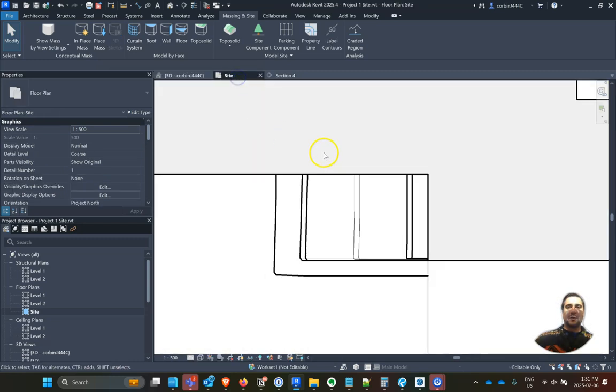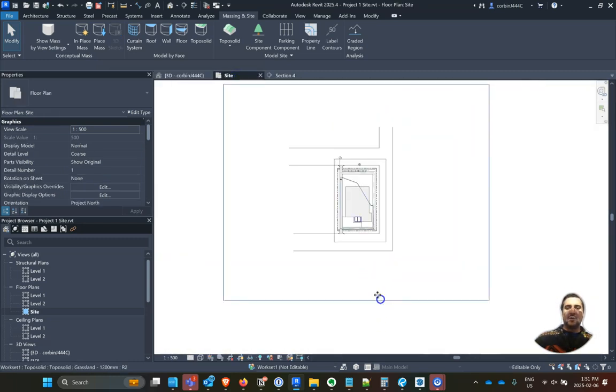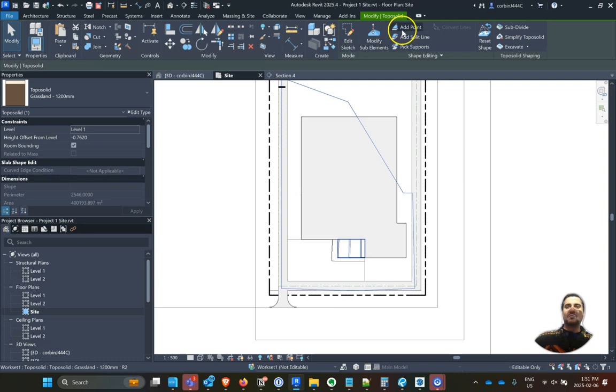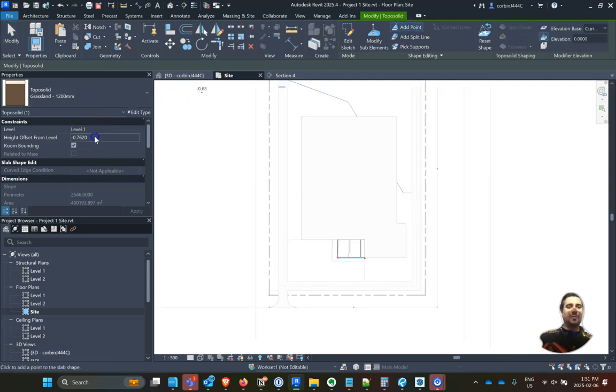And then going around the rest of the building, it's kind of the same concept. That part's obviously the hard one. But with this, we'll just add a point, and up here we'll go to our absolute and do negative 0.15, so 150 millimeters or 6 inches. You could also just type in negative 6 inches, and Revit will automatically do the math for you and convert that into millimeters. And now we could just click these points all around our property for those other areas.